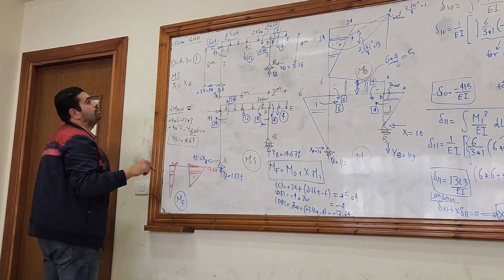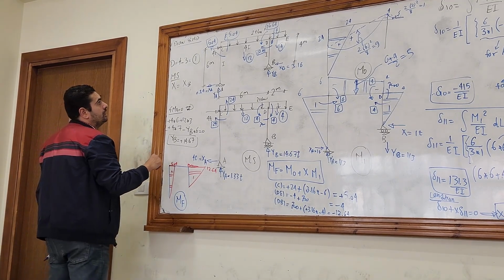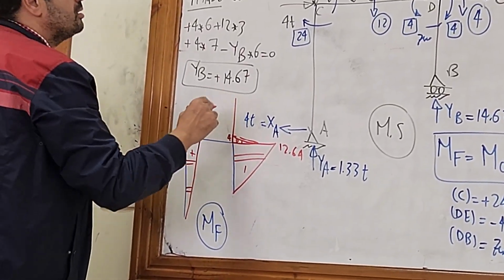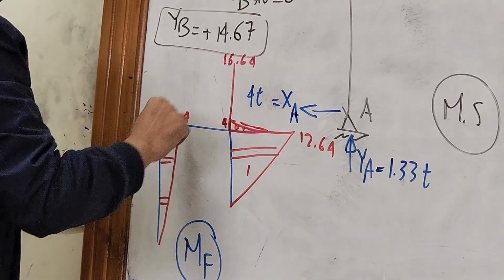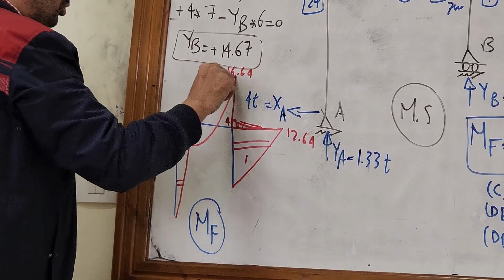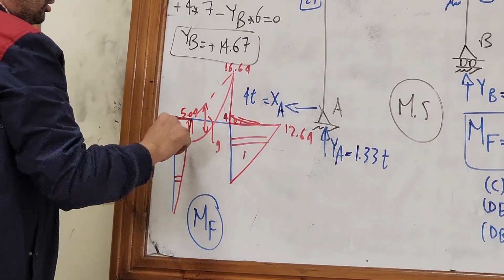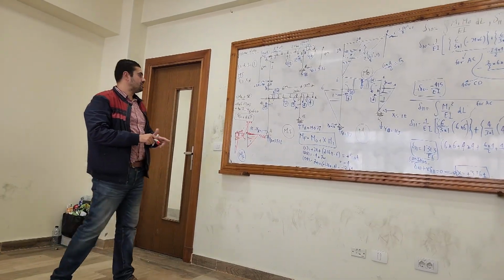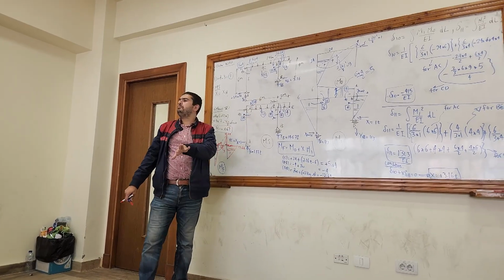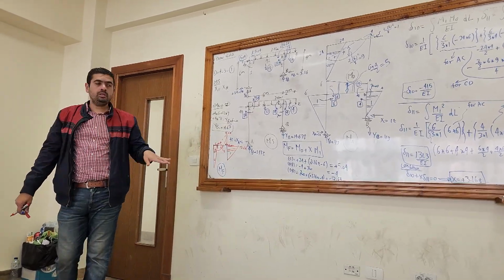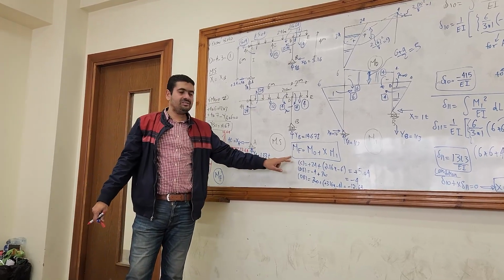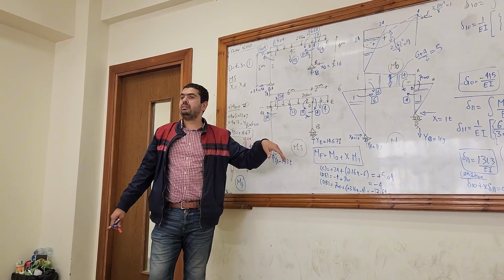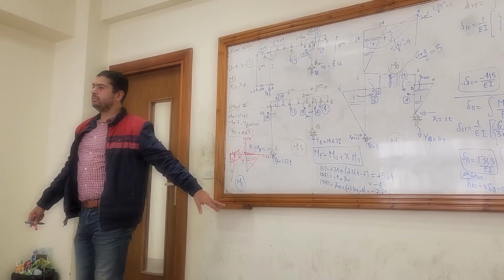For the horizontal member CD, it is 5.04 downwards at C, and at D it is 16.64 upwards, join, and then PL squared over 8, which is 9. This is that one. So you have the two options. Either to draw the bending moment using the same way as in the superposition, or using this easy equation to calculate only the moment at the joints. And when you calculate the moment at the joints, you can easily draw directly the final bending moment.